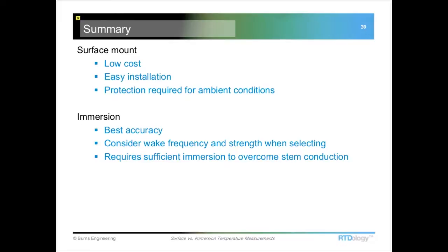Accuracy is not the best, but in situations where you need a temperature measurement and you can't cut into the pipe or the tank or whatever it might be, it makes a real good solution. The immersion sensors will give you your best accuracy.